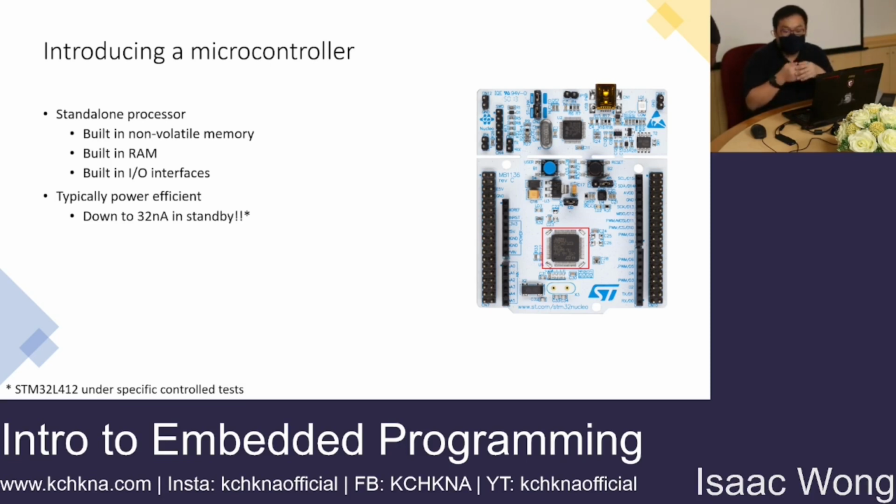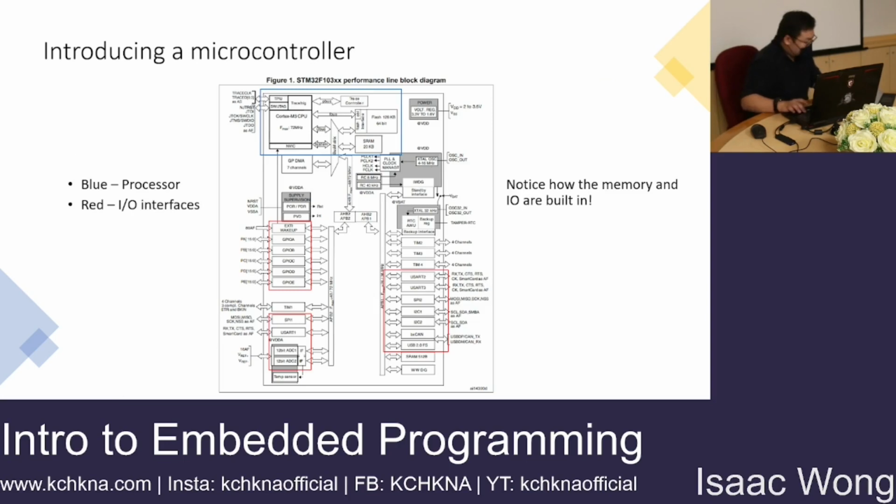Now I'll be introducing a microcontroller, which goes in the heart of most embedded systems. The microcontroller, which I've highlighted in red at the bottom right corner, is that tiny little IC, or integrated circuit. It is a fully standalone processor. By fully standalone, I mean that it has its own non-volatile flash memory right inside it, and there's a RAM inside as well.